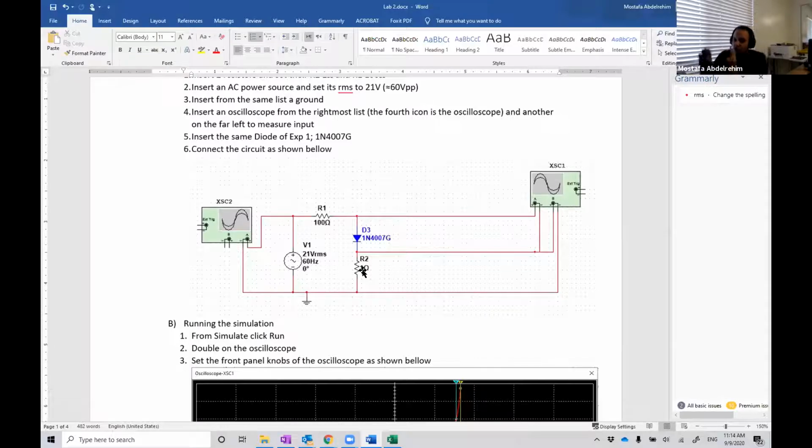They can only draw voltages, just like a voltmeter. But since the current is equal to the voltage across this resistor, if we plot the voltage across this resistor on the oscilloscope, it will be just like the current. Good.